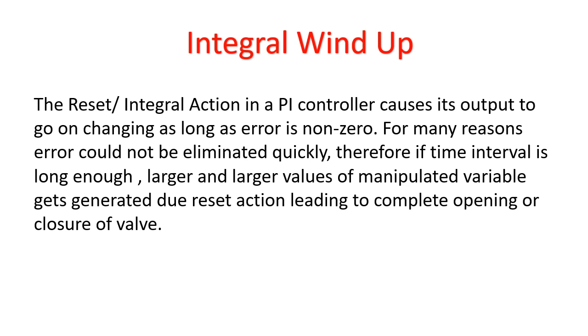And if the time interval is long enough, larger and larger values of manipulated variable get generated due to the reset action, leading to complete opening or closure of the valve. This particular situation is known as integral windup or reset windup. We can also call this situation the saturation of the controller, because we cannot go further beyond this point.